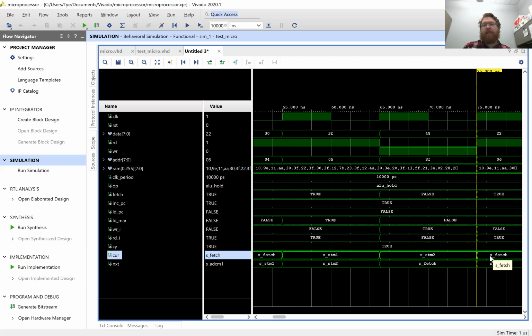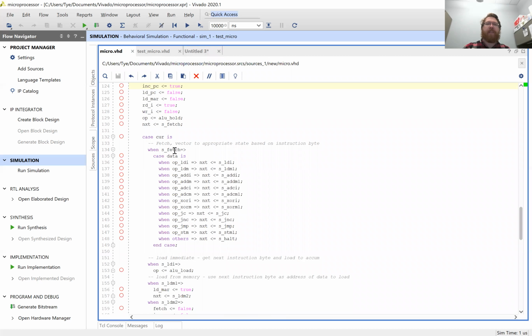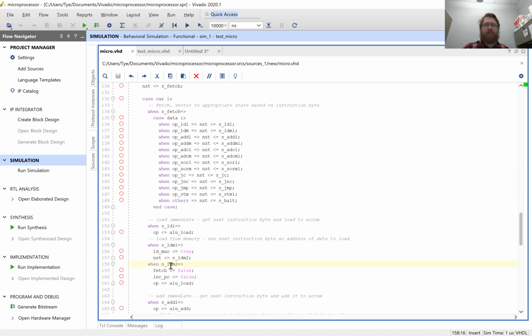Now, what I talked about in lab, the other way of doing this, so this is building the default state, setting the default state to fetch. And we always go back to fetch, grab stuff, and go on. When I talked about it in the lab, what I was doing is inside of this state machine, instead of having the default state as fetch, I didn't even make the fetch state. I just kind of was building fetch into all the other states. So once you finished like load 1, load 2, then it would have an if statement essentially that would go and fetch the next and decide where to jump to, because you know once you're done with this next command, the next thing you have to do is fetch.